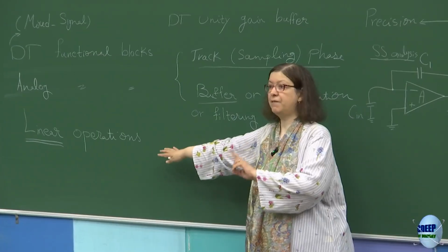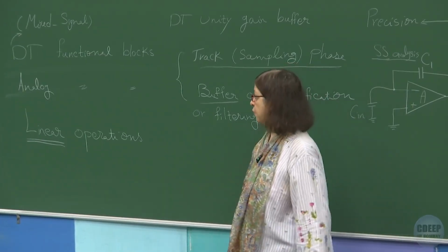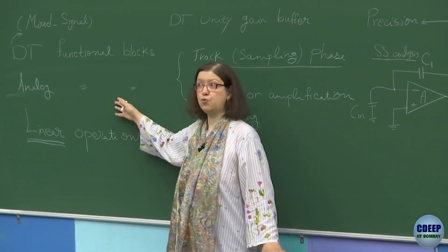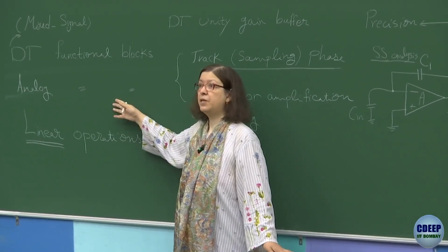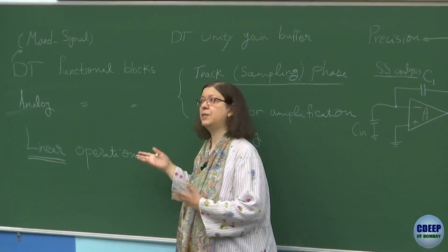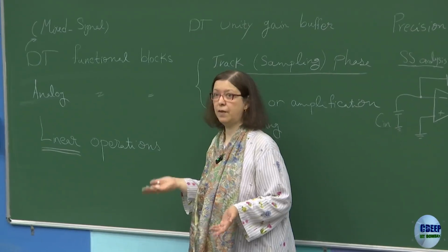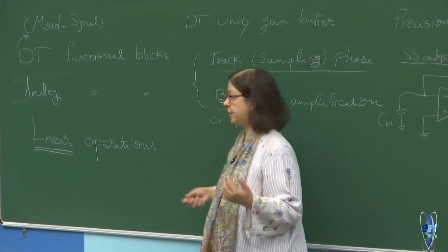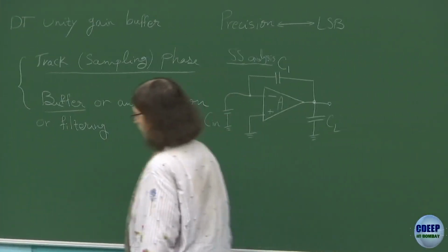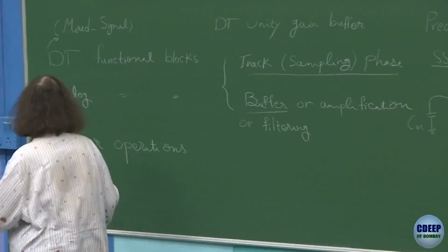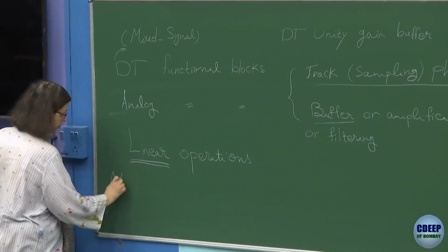I wanted to emphasize this. In this domain, because we are working with switching, even a linear element may get into a nonlinear operation region, and we cannot ignore it. That was the reason that some nonlinearities like slewing come into the picture.